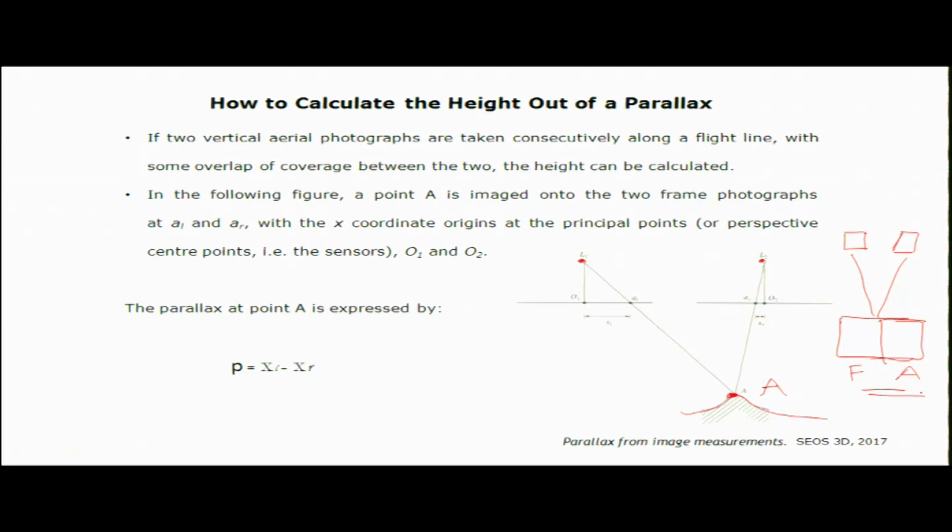In the other kind of photography, there may be a single camera taking photographs of the same plane while flying over it, but with a single camera, and it has some overlap that is set with the camera aperture, timing and the speed of the aircraft.